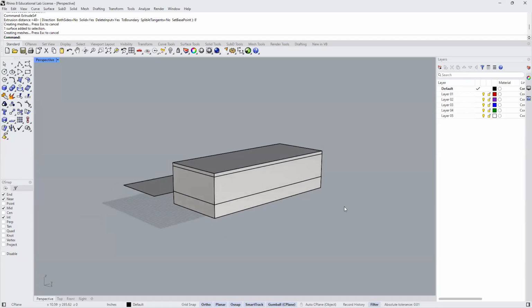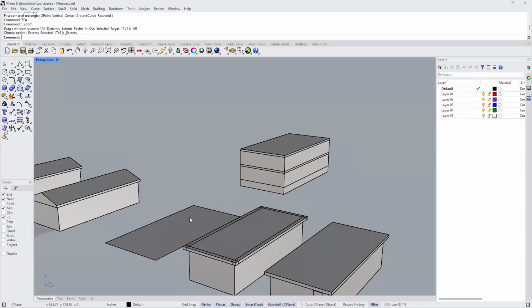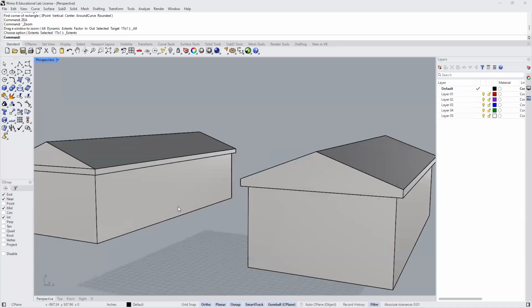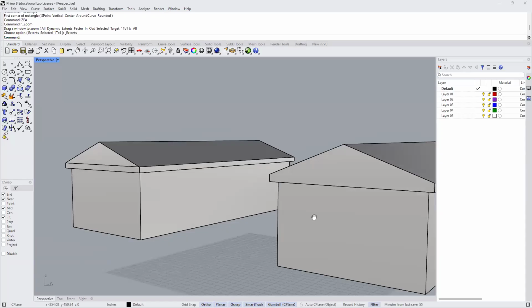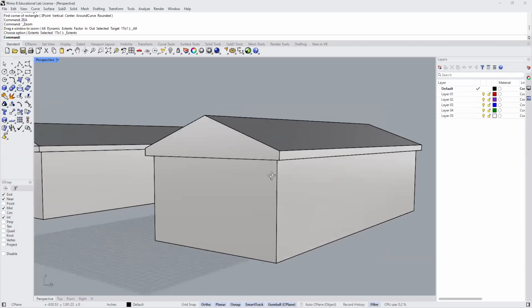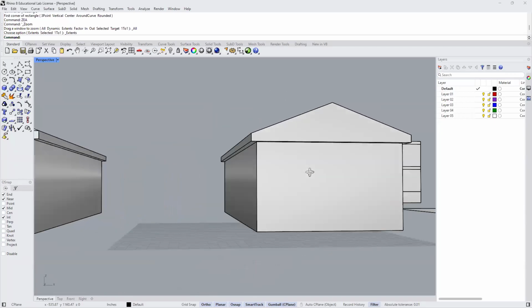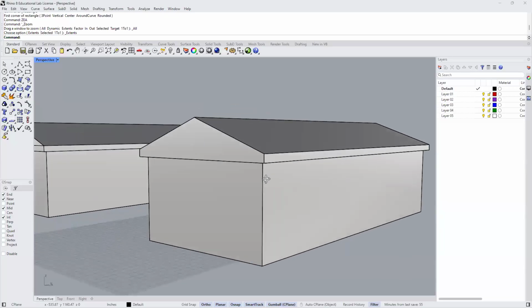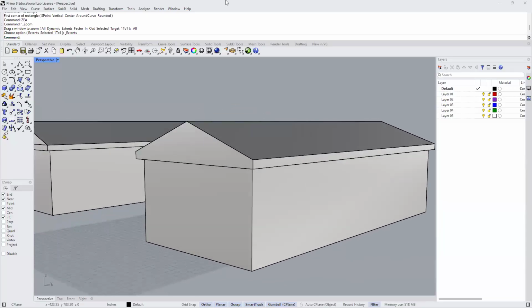To continue, and let me bring back my example here. Zoom this out a little bit. I want you to see that I was providing a soffit. Now let's go to this example here. So I have a soffit, and I brought the soffit out 1 foot or 1'6", can't remember, so that I can get the overhang. And this starts to look more like a house that we see in our neighborhoods. So that's what I'd like to do next, is give myself that offset.